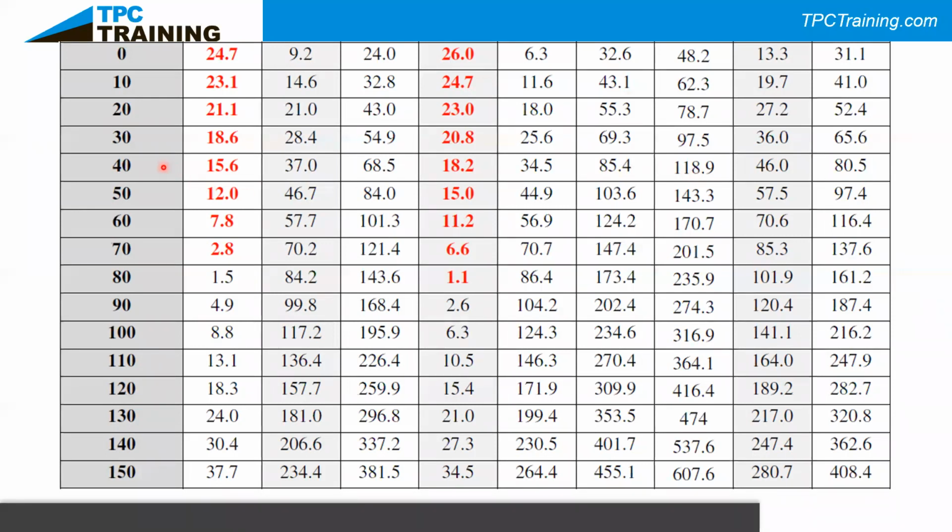Now, another temperature you're going to see: that was our low side. Our high side might be down here, in the 110 range. At 110 degrees Fahrenheit, your R22 pressure is going to be 226.4, but it rises to about 364.1, pardon me, for R410A. So a higher pressure means a higher temperature, and a lower pressure means a lower temperature, but every refrigerant has a different pressure-temperature relationship.